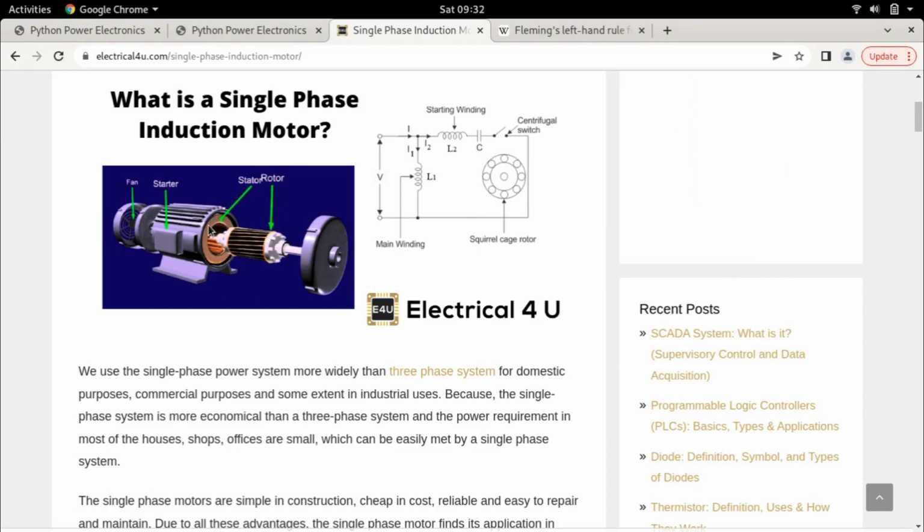The stator slots are all over the stator, the entire circumference of the stator. So it's not just diametrically opposite at 2 slots. You want to use the entire stator as much as possible, because that's how you're making the most use of your magnetic material. Because remember, the biggest cost and the biggest bulk is always iron. So therefore you want to use your magnetic material as much as possible. So you're going to try to put as many slots all over the stator and try to utilize your magnetic medium to the maximum. Right?